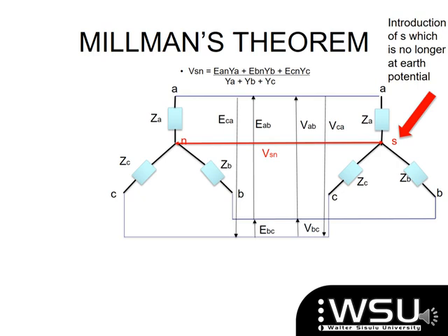So if you're given a reference, which is your line voltage, either AB, BC, or CA, you must know that that voltage needs to be divided by the root of 3, and you must draw your angle accordingly so that you know, if it is a positive or a negative phase sequence, that it will either lead or lag the line voltage that you have been given.